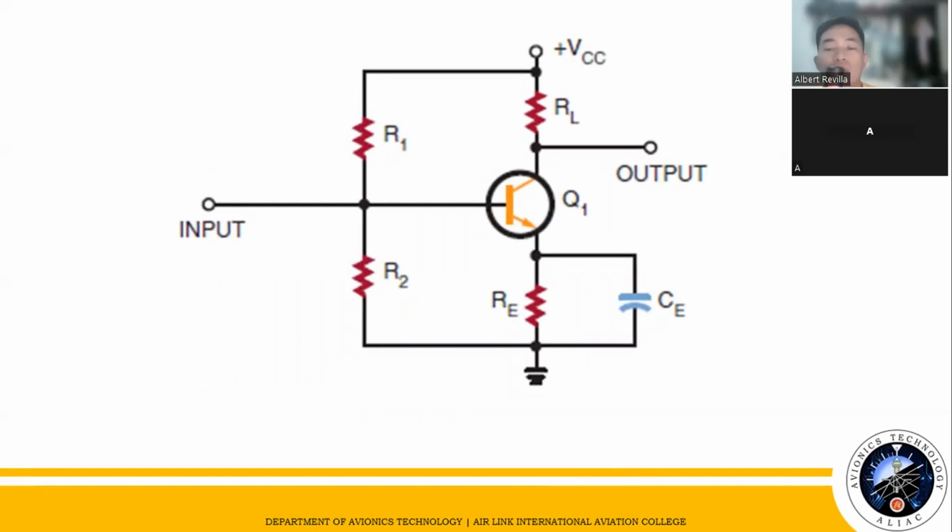So because the emitter current flows through the RE, the voltage drop across the RE is more positive at the end that is attached to the emitter. So the emitter-base junction voltage is the difference between the two positive voltages developed across the R2 and resistor RE. So for the proper forward bias to occur, the base must be slightly more positive than the emitter.